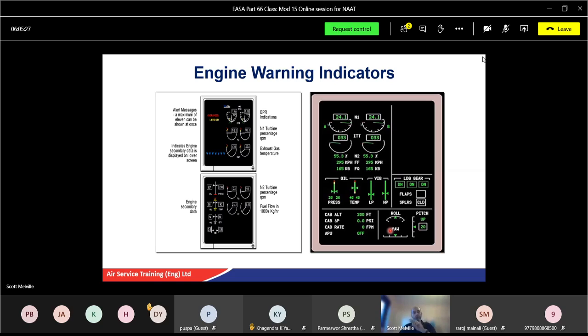We'd actually draw the standard overlay on the screen, or on a bit of clear film. So when you're doing a live vibration run, you see the vibration in real time. Any spikes that come up, we would see come up against a certain point, and we can say, yeah, that's okay, that's the HP pump, just from experience. Again, just a little trick of the trade. But if you ever get a shot at doing it, it's very good.